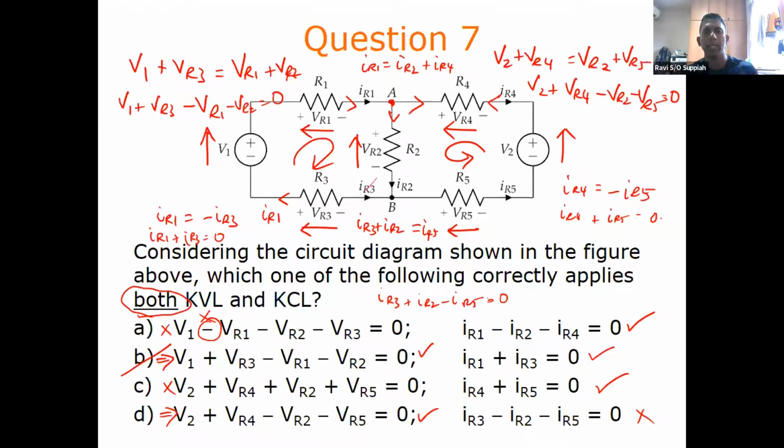When we are solving a circuit, since we do not know exactly which direction the current is flowing, we can assume some directions first, and then after we solve it, we will get the actual value. We will get more practice on this in the subsequent studios and tutorials, where we will look at other circuits with actual values.